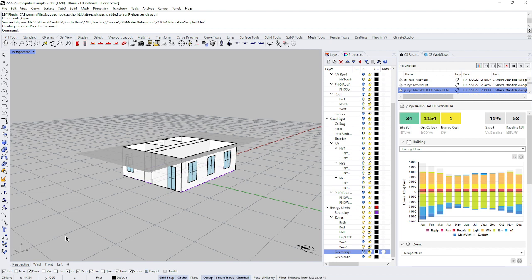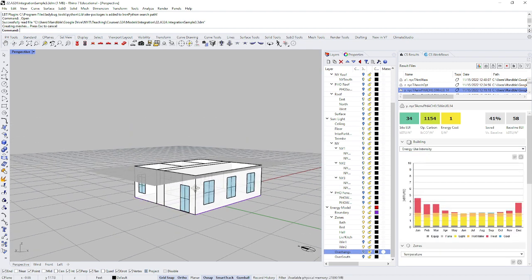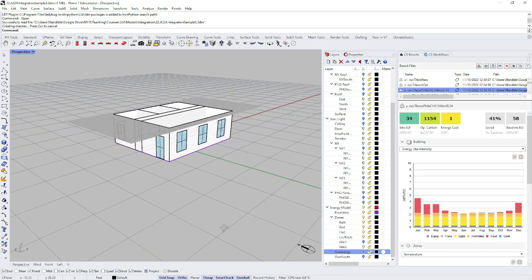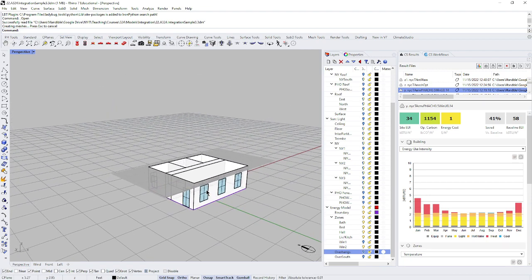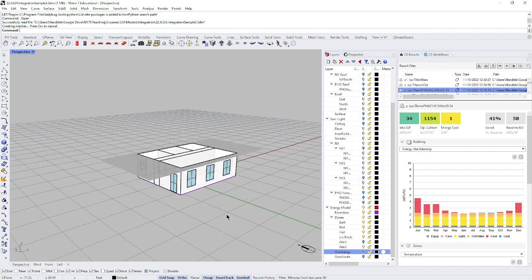I talked about total heat loss and gain, and the reason why was because we were designing passive systems for a single, small building using the site resource, sun and wind, and also designing an envelope that was appropriate for a given climate. As part of the complete building design, we have to talk about how much energy the building is going to use. And we can simulate that in Climate Studio, which we did in that thermal analysis simulation at the end of the semester. We talk in terms of site EUI.